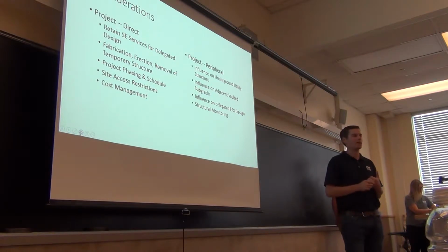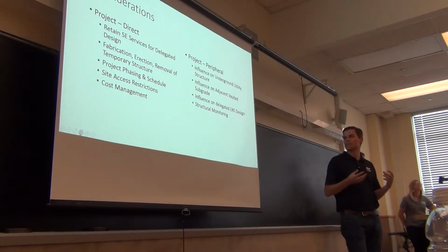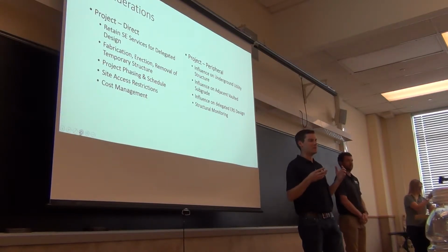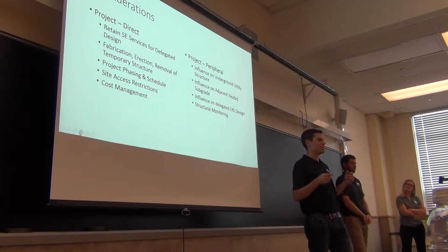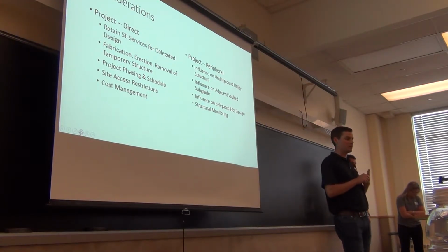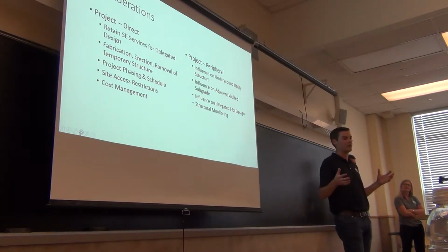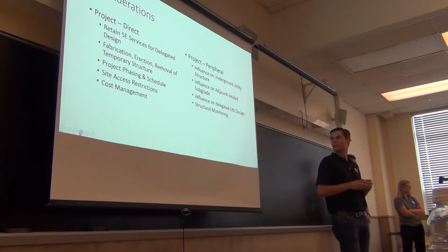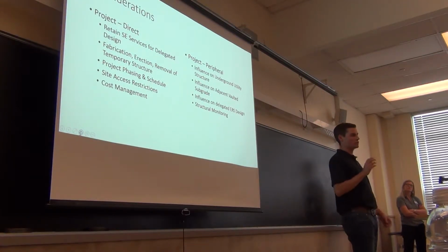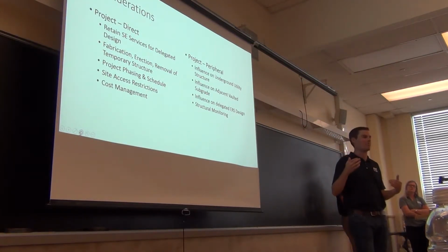Structural monitoring, again, with this being a temporary structure, it's critical to ensure that it behaves in the exact same way that a permanent structure would, because it is every bit as critical. It has to take on the same loads that the columns that were there as part of a permanent construction would have. So as a guard, to make sure that we didn't deal with settlement issues or anything starting to slip, we had to put structural monitoring tags on all of these and monitor daily, to make sure that structure was not moving on us.